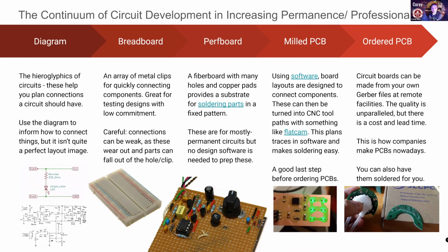A perf board is a great place for maker projects to live, especially when you're just getting started. They're usually simplified circuits. They're relatively nice. Adafruit sells Proto Shields that have perf board on them so that you can put them on top of your Arduino and then solder on the components that you want to make a nice simple circuit. I used to buy those by the gross, actually. So getting a Proto Shield for an Arduino is totally a good way to go if you just want to build a relatively simple thing that sits on top. This is a good way to make it happen.